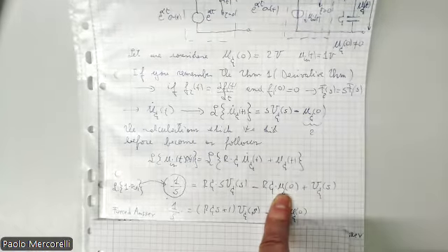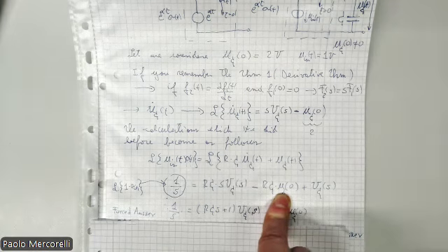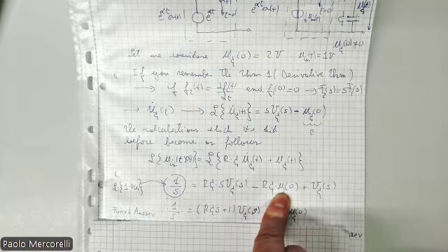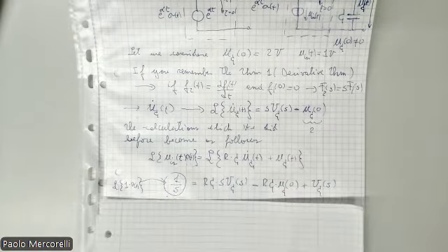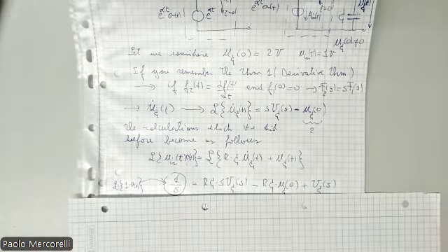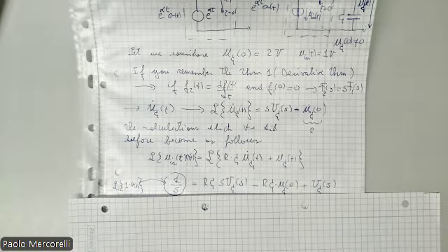But plus, please pay attention here, I put also this element here, assuming that the capacitor is not empty. Do you remember when I presented the Laplace derivative theorem, I presented it with f of 0 equals 0, do you remember? But I told you, if it is not 0, I have to consider minus f of 0.